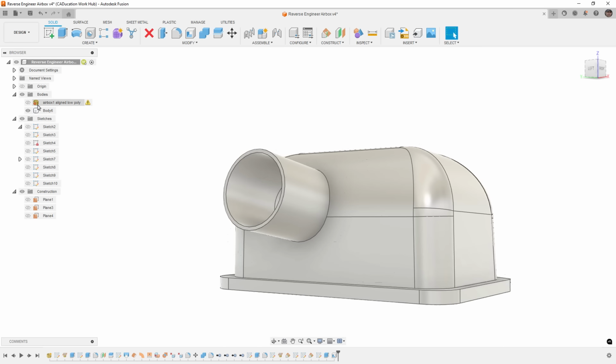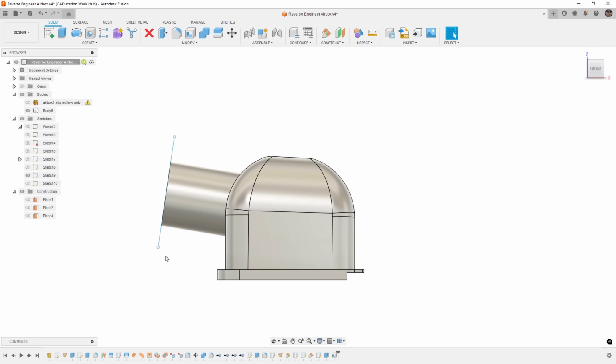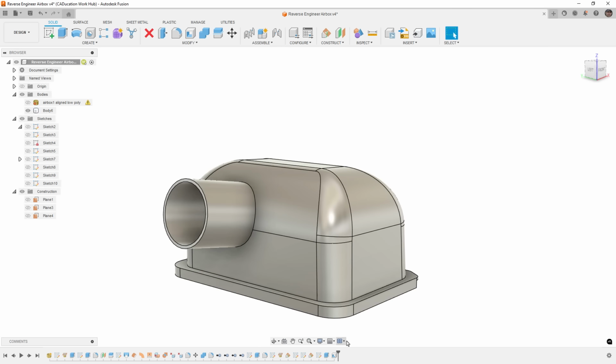Now, in reality, I think that wall is actually a little bit thinner than 3 millimeters, but in general, hopefully that makes sense. Doing those reference edges, whether it's with a mesh section sketch or whether you just kind of eyeball it, and then you create a plane 90 degrees to that. So you take something like the XZ plane and you rotate it 90 degrees to get your geometry. Now, if it's not 90 degrees, then that workflow falls apart a little bit. But in many cases, that can be a very good option for creating that geometry.